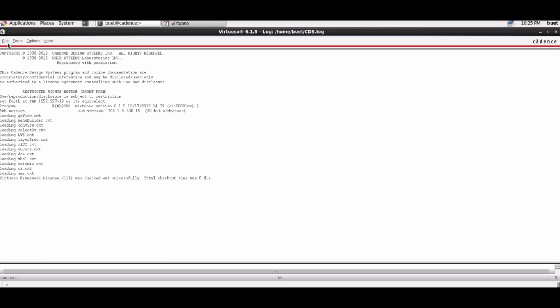Now, there are usually three types of libraries. Number one is a set of common Cadence libraries that come with the Cadence software, containing basic components such as voltage and current sources, RLC, etc. The second one is the library that comes with a certain design kit. For example, we will be using GPDK090 in this lab, and that are related to a certain technology. For example, transistors with a certain model attached, etc. Then there are user libraries where the user stores its design.